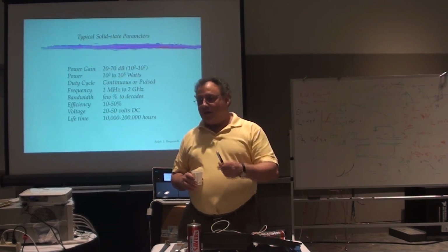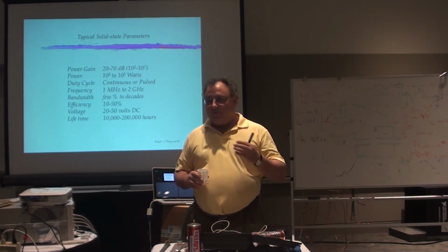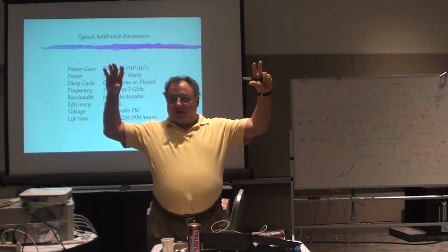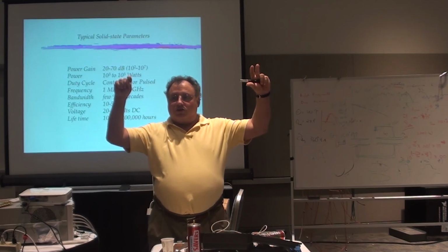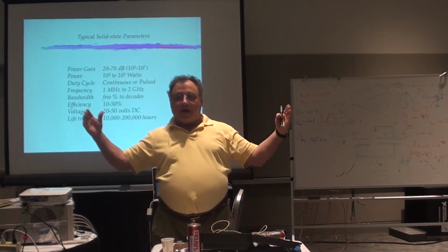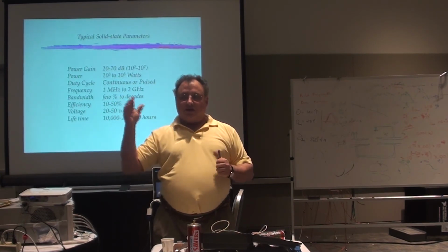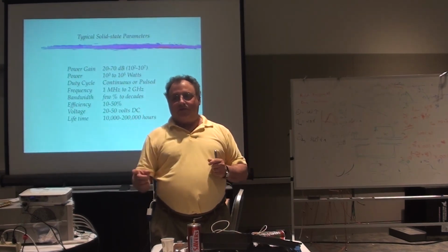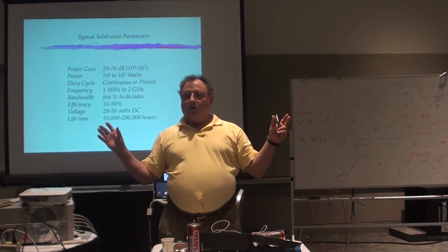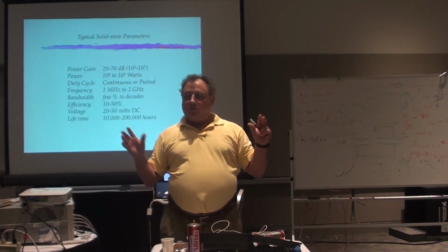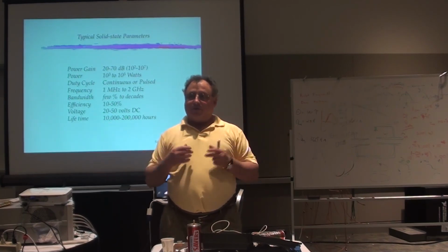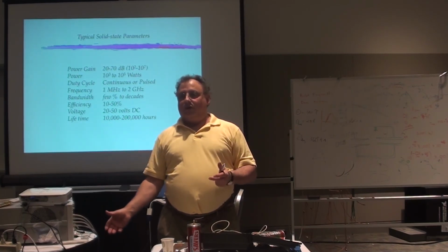Like the amplifier we just bought, they built in a protection system. There are 8 transistors in each slice, and if one transistor goes, it allows the amplifier to continue running. But now it's put a mismatch in the combiner tree. And so they said, even though this amplifier is made to do 75,000 watts, as soon as one of those transistors blows, you can't do more than 50,000 watts. So you can run, but is 50,000 watts enough? If it isn't, you've got to fix it. If you have to fix it, you're down. Your beam's not running. You're going to get charged for that.